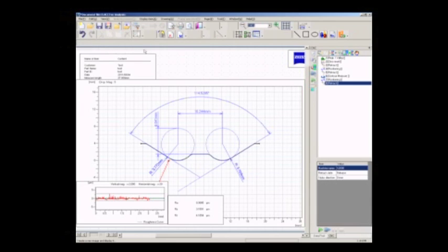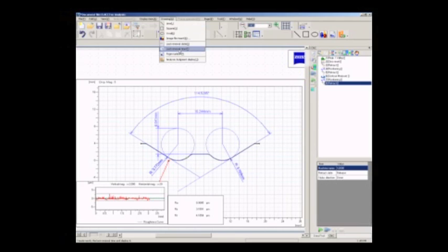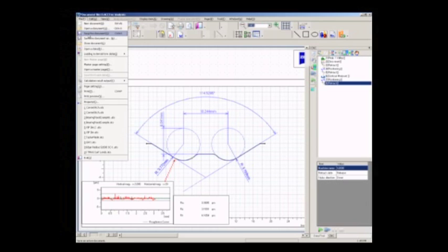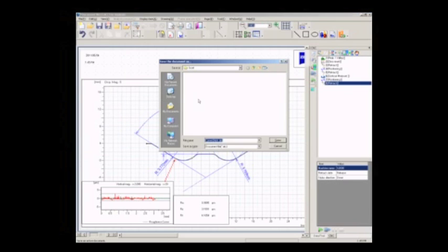Now that I have that, I might also want to add, for example, last renewal date and a last renewal time. These will update when I execute the part program. So you'll know when this particular measurement was taken. Okay. Now that we have all that on there, let's go ahead and save this part program, and we're saving a document.